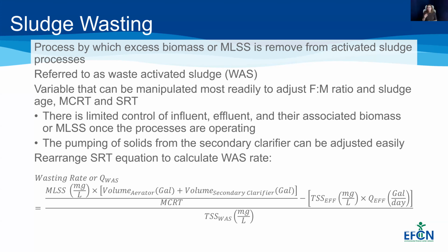Your WAS rate is equal to your MLSS concentration multiplied by the volume of your aerator and your secondary clarifier. You divide that by your SRT, then you subtract the TSS of your effluent times the flow of your effluent. You subtract the product of that from the first part of the equation, and then you divide that whole thing by the solids concentration of your WAS. And in this example, like we said, sometimes you treat your MLSS and your secondary clarifier as the same concentration, if you're not directly measuring that.